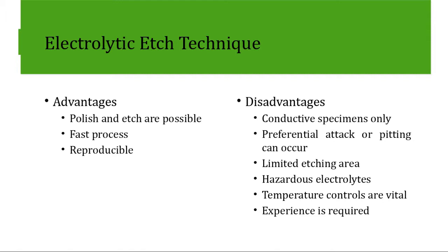So that would be one nice way of doing it. Obviously, if one person has a 4140 and now you want to electrolytically etch an Inconel 738, which is a nickel-based superalloy, you have to find now a new type of electrolyte, identify a new voltage, a new time, and of course temperature is always going to be a factor.